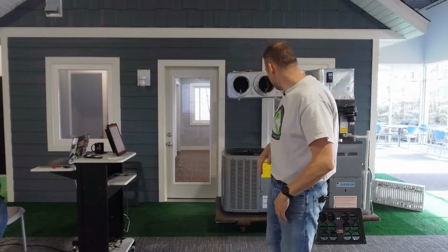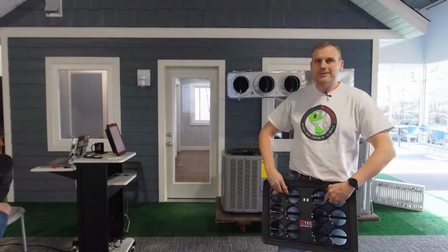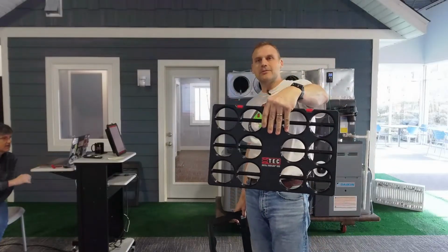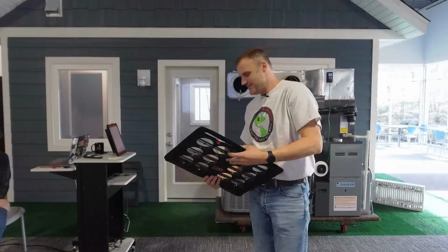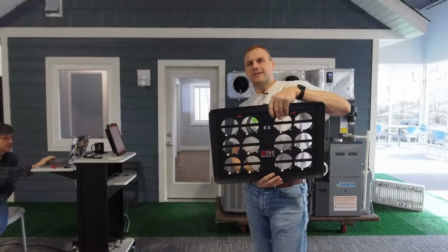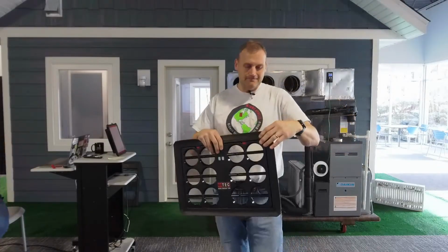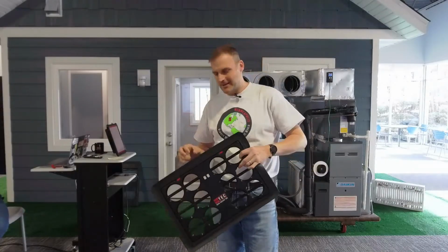Now, just to kind of, once again, ground the conversation of what are we doing here? So we're going to be talking about the Digital TrueFlow grid, and this is a total system airflow device. So it is grid, right? It goes in where the filter is located. You have an adapter plate that it's going to snap into, and that allows it to take the place of the filter. The adapter plate's purpose is to seal airflow where the bigger filter would have been that's bigger than the grid. So that's the point of the adapter plates that it snaps into.